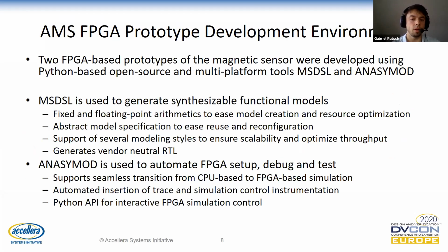Before I go into detail about the two FPGA prototypes, I would like to spend some words on the two frameworks, and point out the most important features there. As I said before, MSDSL is used to generate the synthesizable function models. One of the key aspects that make it convenient to use for that is that you can make use of a SystemVerilog library that enables a seamless transition from a fixed point to floating point representation of the arithmetic operations.